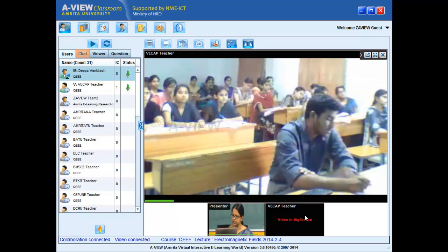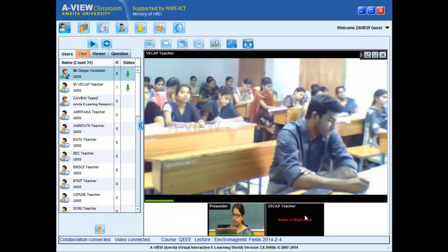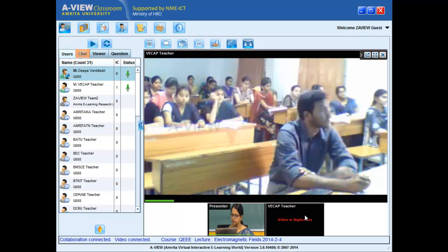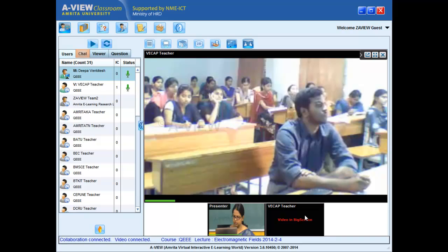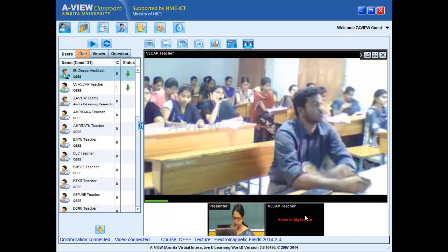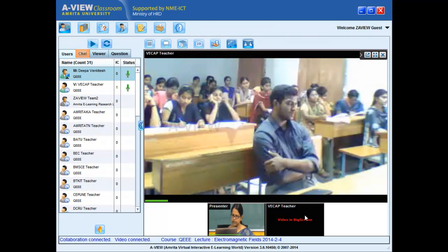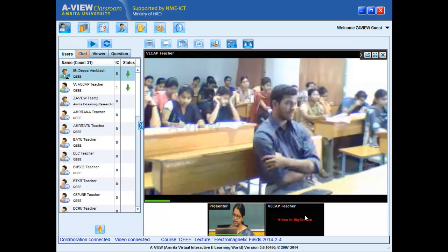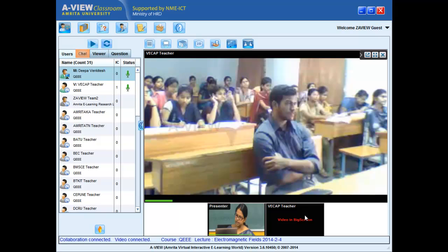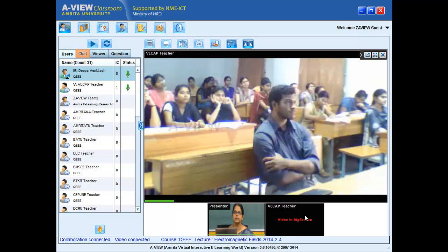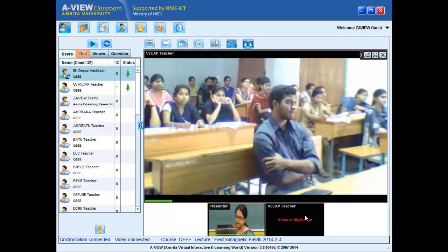What would Kirchhoff's current law say? It's current branching law. You had I delta Z, so you apply it at this junction, say C. Applying KCL, what do you get? You have I reaching this, and then you have a branch current passing through C delta Z and passing through G delta Z, and you have I at Z plus delta Z coming out of the branch. So you have current entering, and you have current leaving, and you have a current leaving.